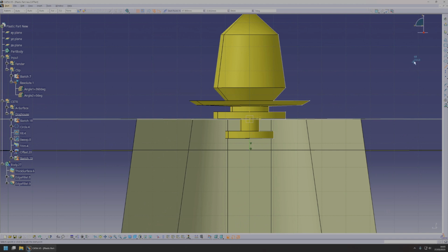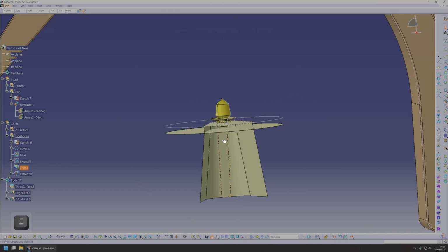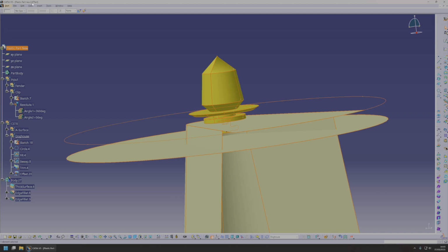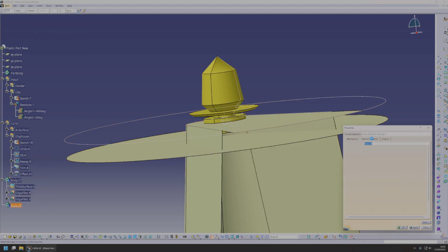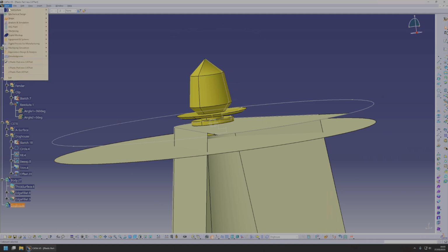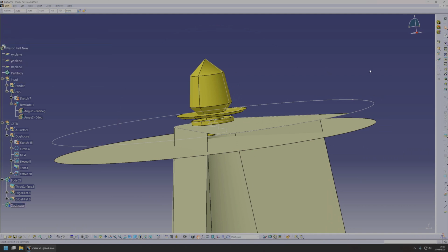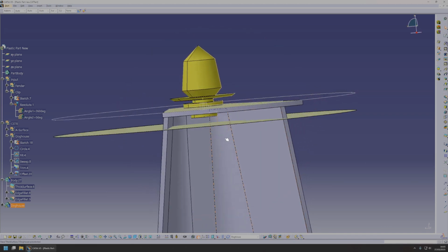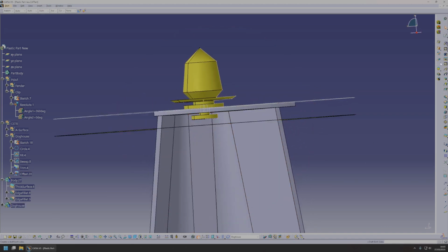We'll create a rib here. The idea of this rib is that I want it pressing on the clip to keep it locked into place. Now, like I always said, I want to be able to visualize what I'm doing here. So we will create this and call it Doghouse. And we will switch back to the mechanical design. And we will give this some thickness. 3.5, that's good. We need to put some thickness in here as well.